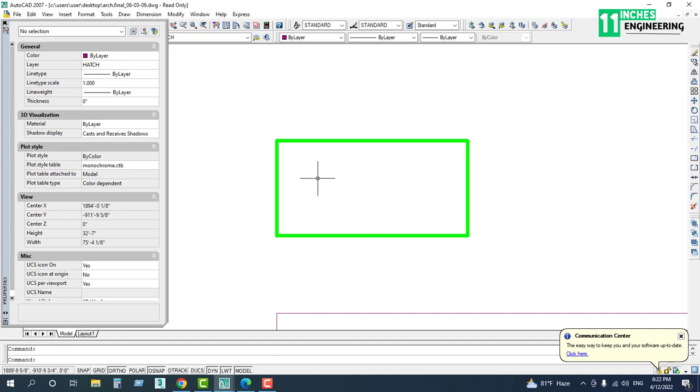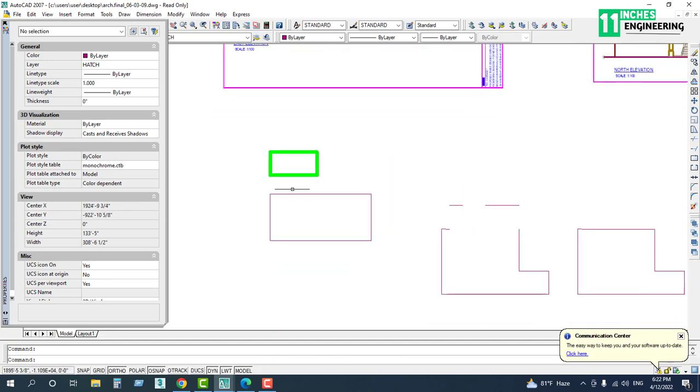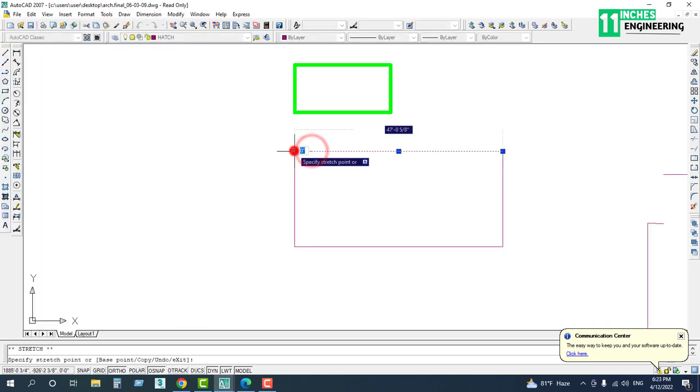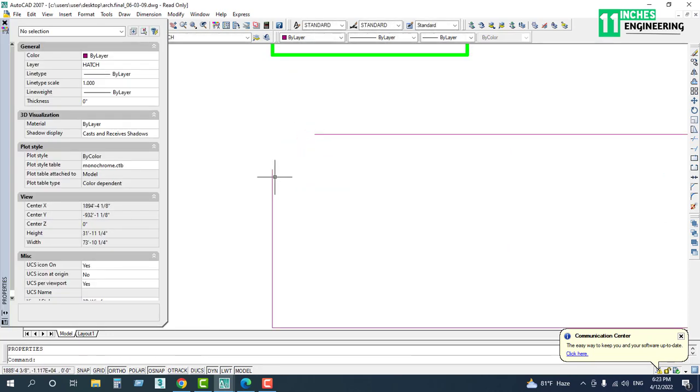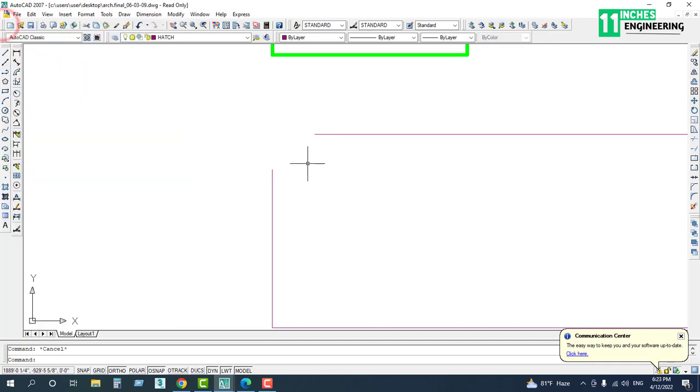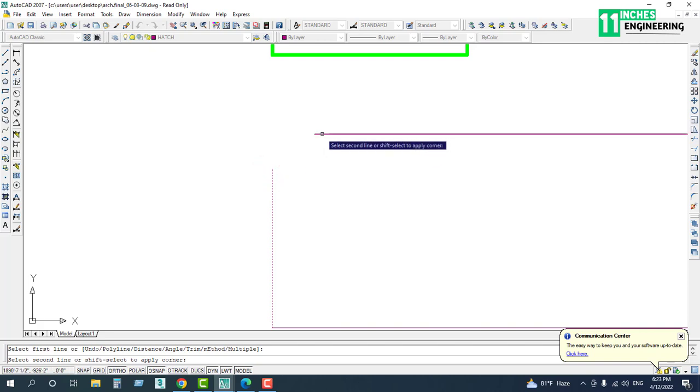Alright, now next, CHA, chamfer. Sorry, CH will bring the properties palette, and CHA, enter, then first line and second line.